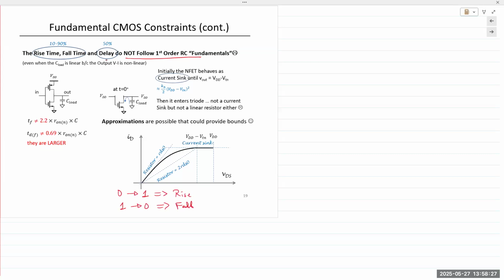So these, let's see, rise time and fall time. I had an equation. Okay, right here, 0.29 and 0.69. So the rise time and the fall time for these devices would be different because of the physical construction of the device. So again, that is another physical constraint on the operation of these devices.